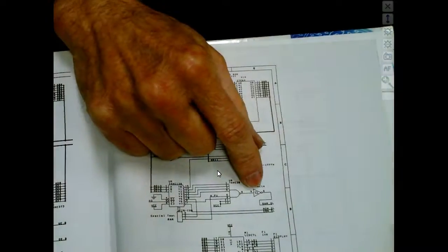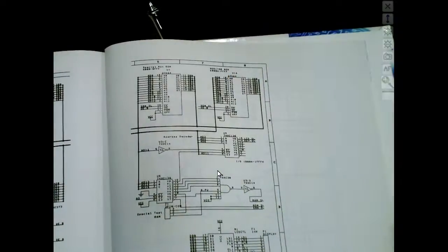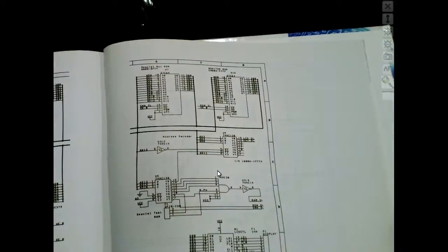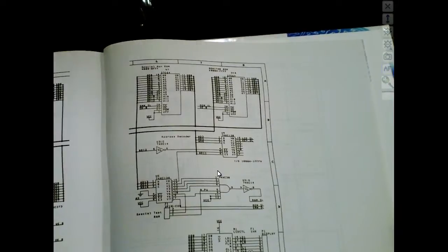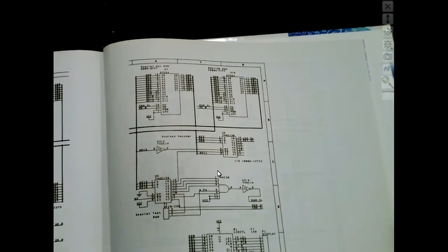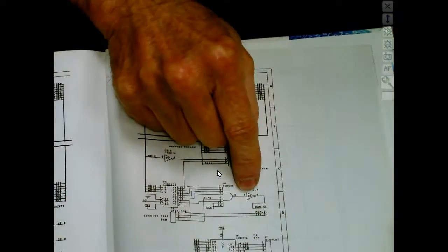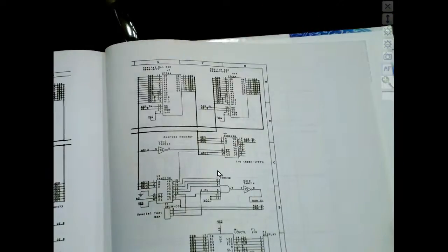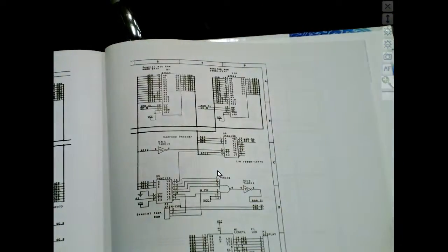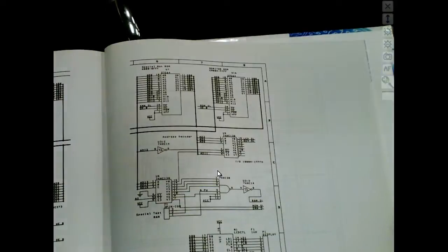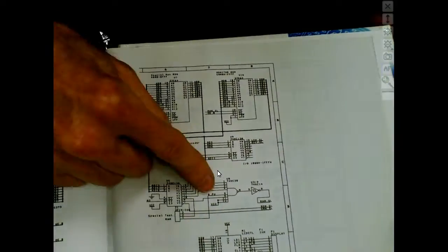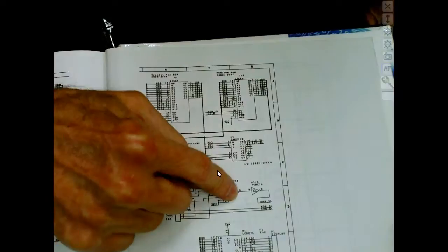It was originally developed for magnets. When you magnetize a material, how much energy does it take to magnetize it in the opposite direction? And it came up with this thing we call a hysteresis loop. So that's this guy right here. See the little symbol right there? Normally we use these things on digital logic circuits that are getting information from the outside world, because you can understand that those signals meander all over the place. So these are called Schmitt triggers.